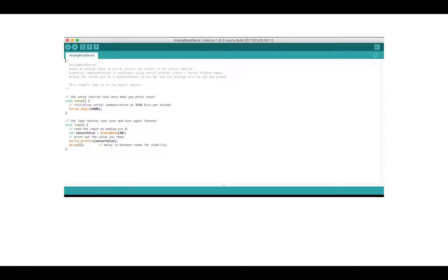Okay, let's talk for some time about how this creates the random numbers. There's a question. The ADC pin has to remain in the floating state. That means pin A0 should not be connected to VCC, ground, or any voltage source. It should be left open. So why does such an effect create random numbers? That's a question, which I'm going to talk about in the next slide.